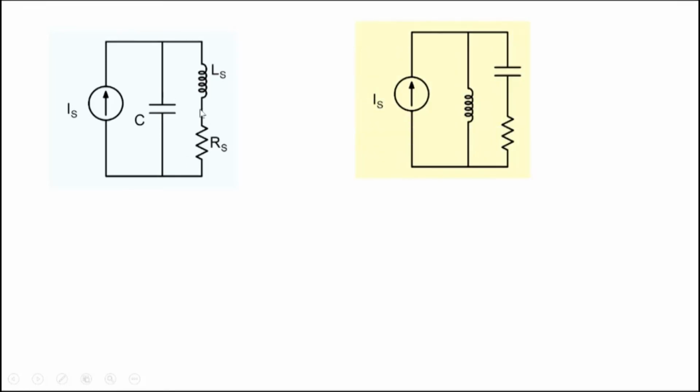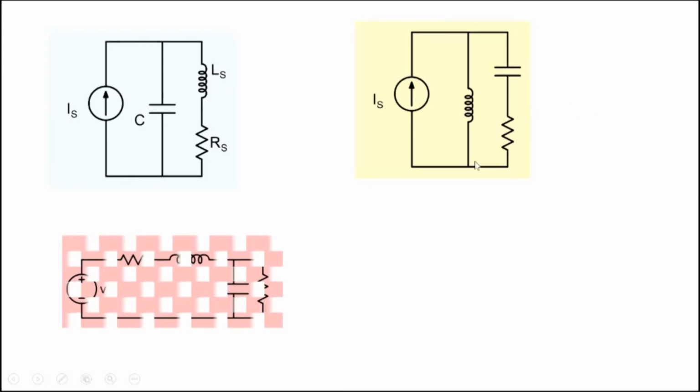So we can also have circuits like this here. We have an L and a C and an R. And again, this does not fall into the results that we have discussed, but the series combination of C and R, you can transform it into a CP and an RP in parallel. Using the same approach that we used here, you could use the same approach here also, and thereby transform it into a completely parallel circuit.